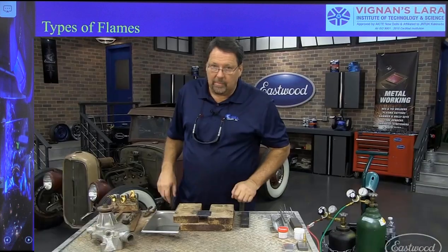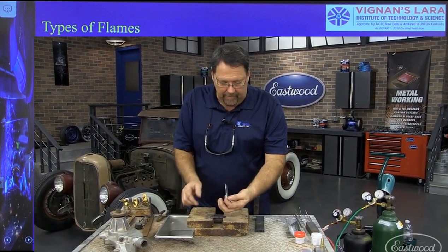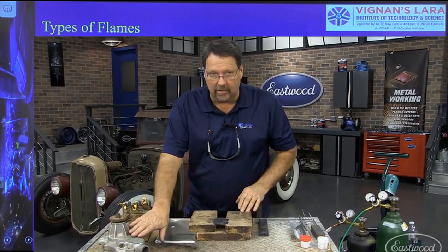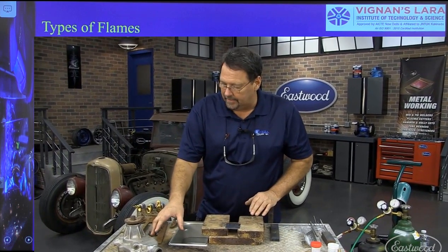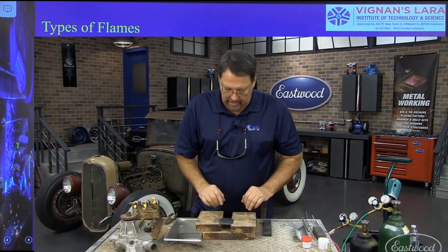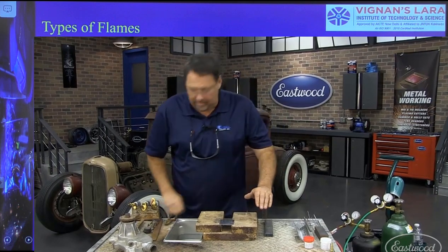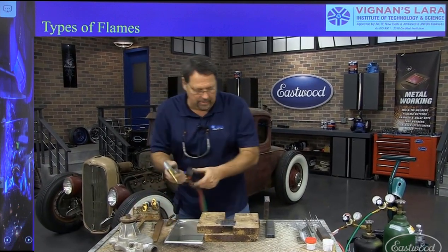Okay, now I'm going to show you some aluminum welding using the DHC 2000. We're going to do some thin body aluminum here, it's 035, and I'm also going to show you some cast aluminum, how we repair a cast water pump, might be a water jacket. We can do it all with the torch. So let's go here and do the body aluminum first. I'm running at 4 pounds of oxygen and acetylene. Let's go ahead and do this weld.